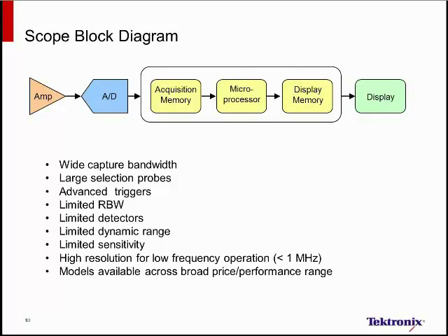When I think about sensitivity, oscilloscope sensitivity is in the millivolt range. Spectrum analyzer sensitivity is in the nanovolt range. So we're going to see a lot more detail with a spectrum analyzer versus using an oscilloscope. Depending on the oscilloscope you have, the FFT capabilities, or the ability for us to visualize the spectrum with the scope, varies widely. If you have a general purpose oscilloscope with an embedded operating system, you may or may not get full control over the FFT calculation, meaning you might not be able to set reference level, you might not be able to set resolution bandwidth, and you might not be able to select detector type. All of this is going to affect how well we do the EMI scanning.